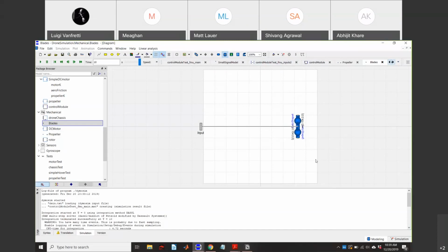So this will at least have the kinematic dynamics, the Newtonian dynamics for this multi-body system. Whatever the torque delivered to the motor to be able to move these lumped masses is going to be a better representation than having just a fixed value, for example, or a table. Because if you have a table of values, you can't really capture any dynamics of that. So this is a simplified way of representing this, and this is the idea with starting with very low order models.